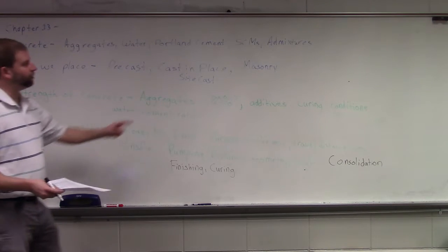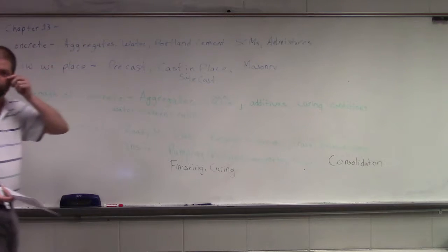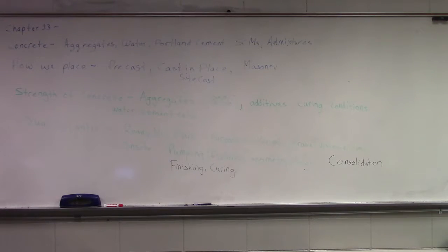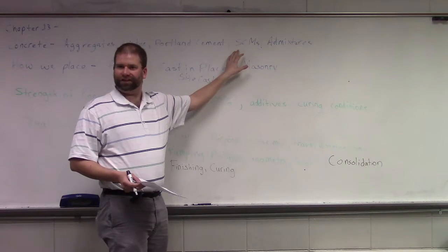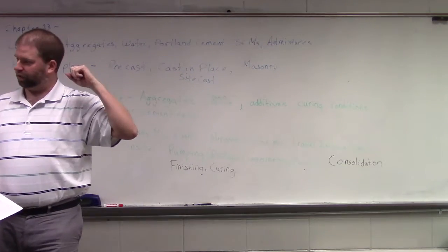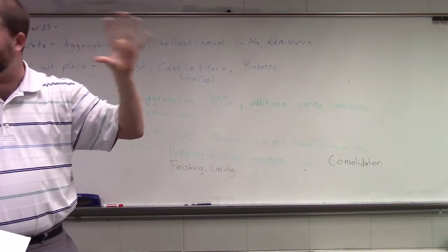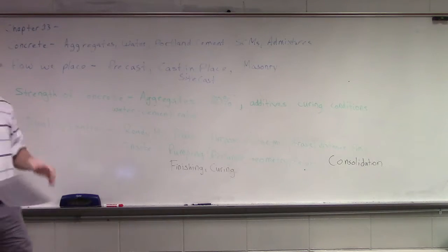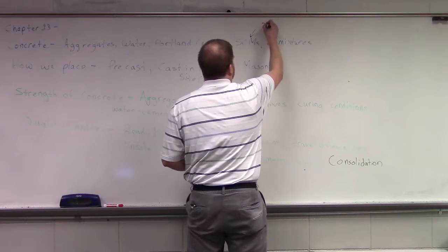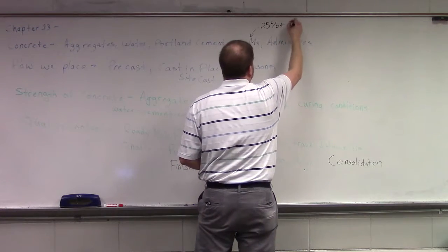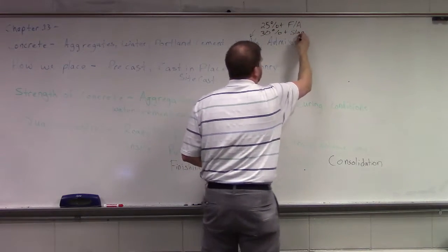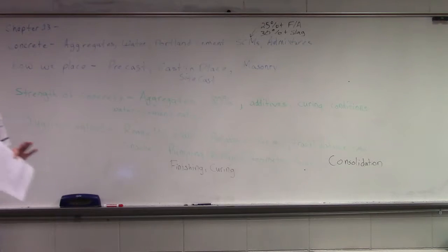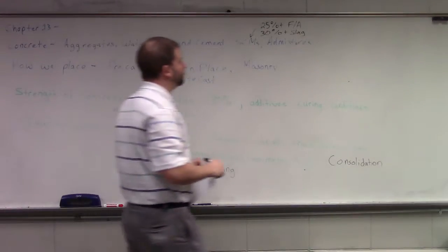One thing to be mindful of, especially with these SCMs, if you're working with specifiers or if you're doing specifying, be careful. Typically people are going to be specifying a 28-day age test for acceptance. If we're doing massive structures, like dams, where we're using a lot of these SCMs, by a lot I mean 25% or higher of fly ash and about 30% plus of slag, I would recommend that you push your strength test out to 56 days, okay? You can still perform a test at 28 days, and if you get that strength, that's great.